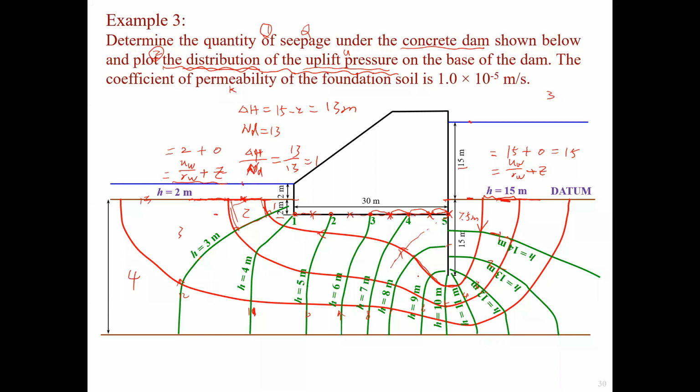Oh, so the red line, we can choose anywhere and then we just draw them. Yes, but based on common sense, you plot three flow lines, 2 to 4 flow lines, roughly in this shape. About the curve, we have to follow the height line. The right hand side goes down 15 meters, so we have to start from 15 meters. Oh, all right. Okay.